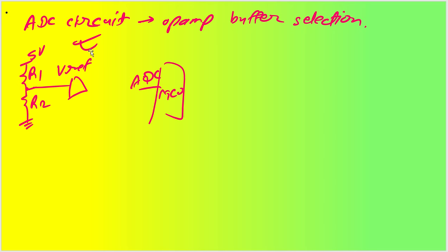microcontroller. So this is one of the essential required skills: how you are going to voltage divide your input voltage or any other parameters. Let us say you have temperature sensor outputs or pressure sensor outputs or anything. All of them need to go to the ADC channel, and the ADC will give you the value which will decide what the actual analog value was. Okay, so for that we definitely need either an amplifier or an op amp as a buffer. So those things will be needed.